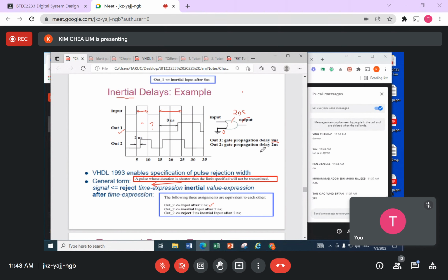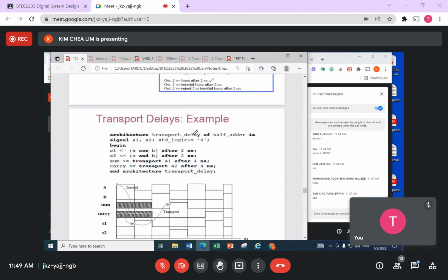So in this case, if the signal is faster than the inertial delay of the gate, they just don't respond. Just like our eye, don't respond. Couldn't see, don't know who that person is. All right, so no signal is detected at the output. Okay, so this is the inertial delay, but all the timing here will be in terms of nanoseconds, this type of part.